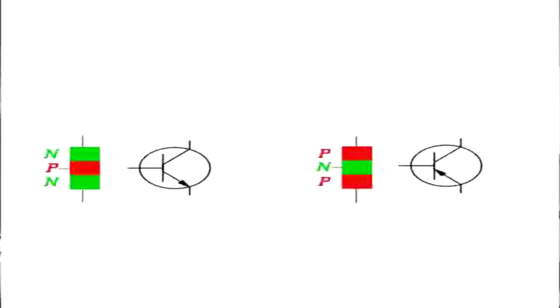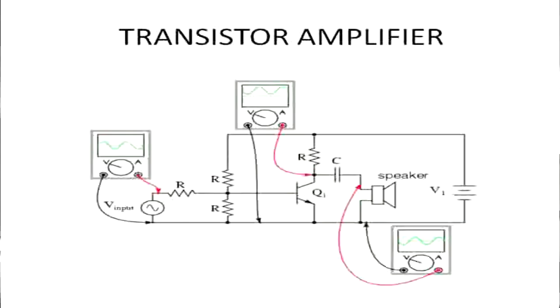Here is a transistor amplifier. We've got our signal coming in. We've got a bias. The signal is going to the base of the transistor. Current flows up through the emitter, through the collector, through this resistor. DC is decoupled, and the speaker is driven. One battery supplies the whole thing. I want to expand on that on the web page because I'm flying through this.